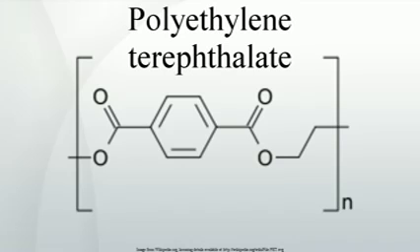If crystallizable PET is used, the trays can be used for frozen dinners, since they withstand both freezing and oven baking temperatures. As opposed to amorphous PET, which is transparent, crystallizable PET, or CPET, tends to be black in color. When filled with glass particles or fibers, it becomes significantly stiffer and more durable.